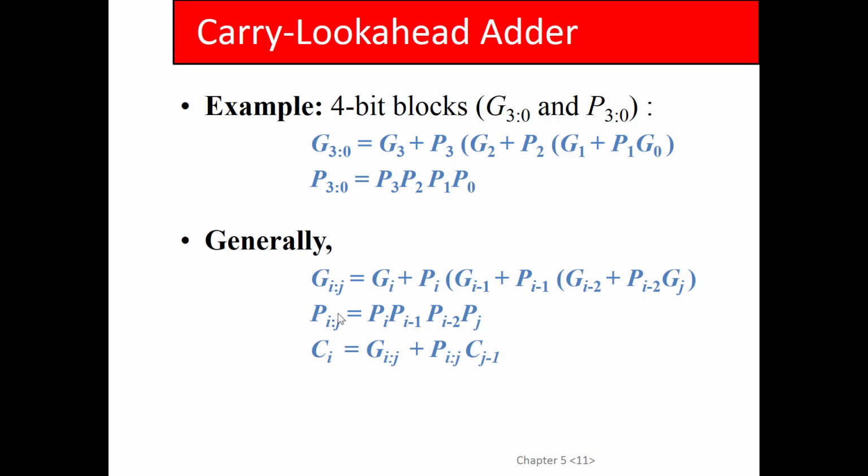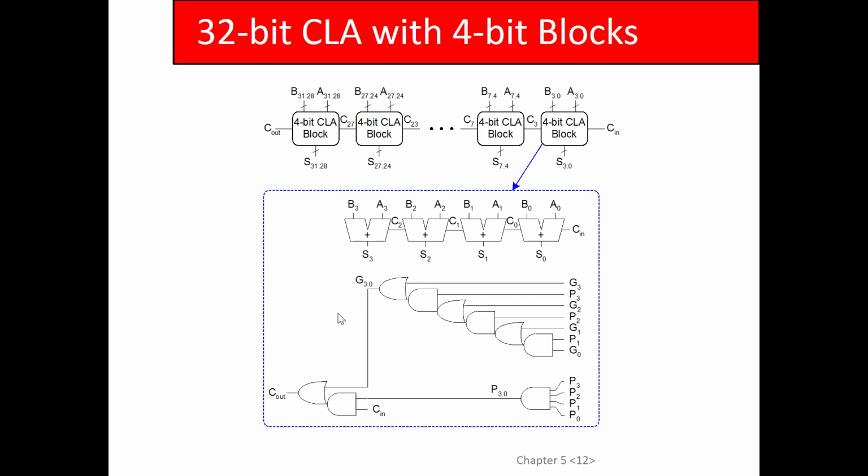So the book shows this diagram. I think this is pretty nice. This is the 4-bit carry-lookahead adder block, which is the way I described it here, where each bit generates its carry in based on the generate and propagates of the other bits in that group. You guys with me? And frankly, you probably don't even need to do that.